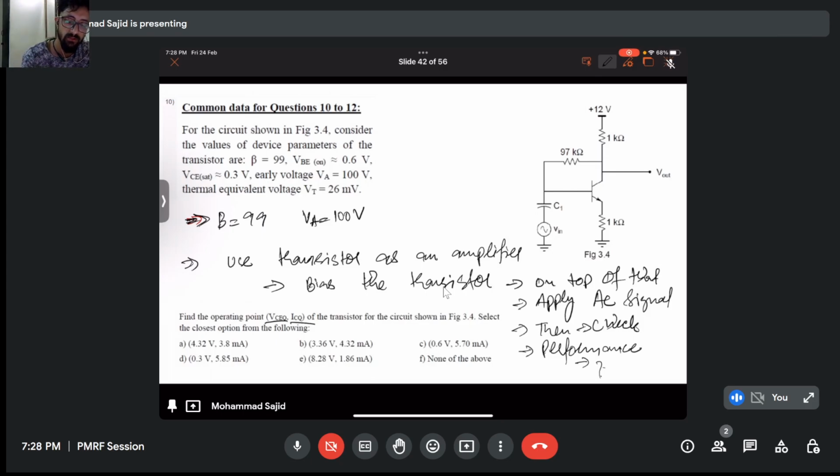Okay, so this is my circuit. This is one loop, right? This is another loop. What is the current that flows in this resistor? Here, DC current will be IB. DC won't flow through here, right? So this is IB, this is IB, and this is IC. If I apply a nodal analysis here, the total current in this resistor will be IC plus IB, and here this is IE.